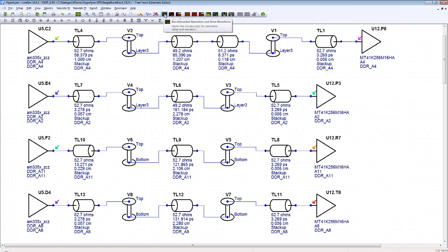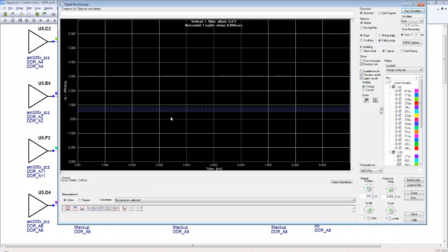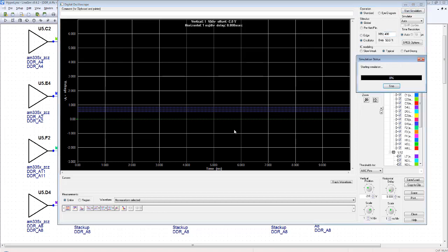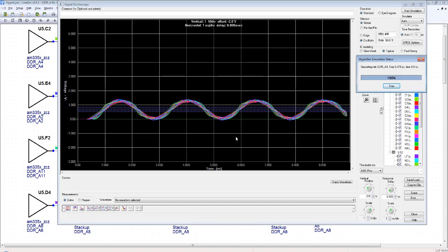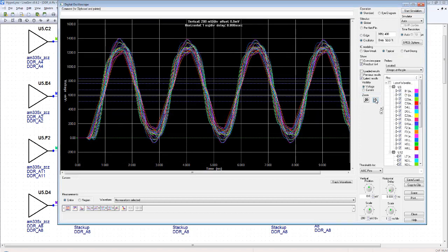I have several options to do a simulation, but for this purpose I make a very simple one with an oscilloscope where I set up maybe 400 megahertz that I like to simulate. I make everything nicely into the view. So I see the waveforms on both my memory controller, which is the ARM processor, and the receiver chips, which are the DDR3 memories. In this moment, I'm only interested to watch the curves on my DDR3 memories.